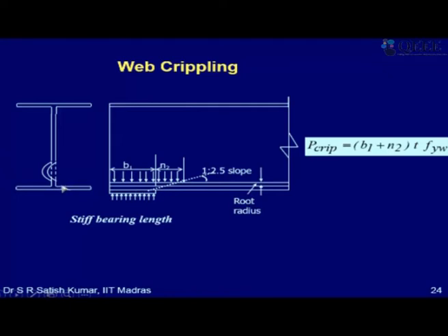but after you cross the flange, in roll sections you have something called a root radius. Okay, so that is why there is one more line drawn here to show that this is the root radius. Instead of that, in a welded section you will have a weld. Okay, so that weld toe size will be the same as the root radius that is shown here. So just above that, all these forces which are there. So in the support you have a wide flange and all the forces are applied there, but then eventually those forces have to enter into the web. So all these loads that you see here on the section have to eventually enter into the thin web. So the web will have a stress concentration problem.